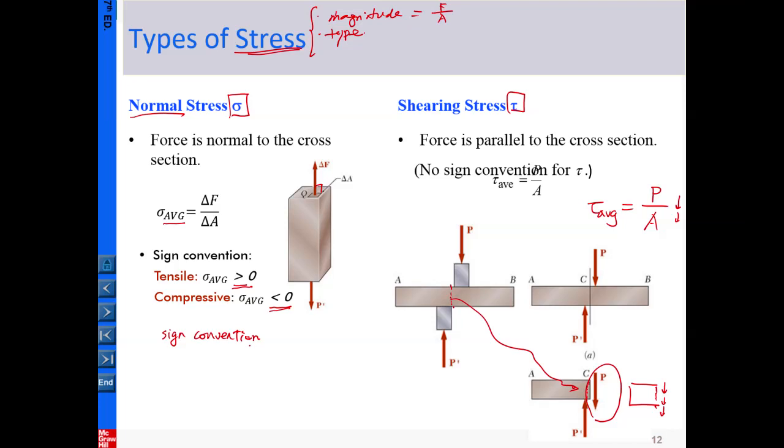If you want to be picky, then you can identify the direction as well. So usually the stress is composed of the magnitude, type and then the direction. For example, direction for normal stress is told by tensile or compressive. The direction of the shear stress, you can just indicate on any graph you are working on in the problems.